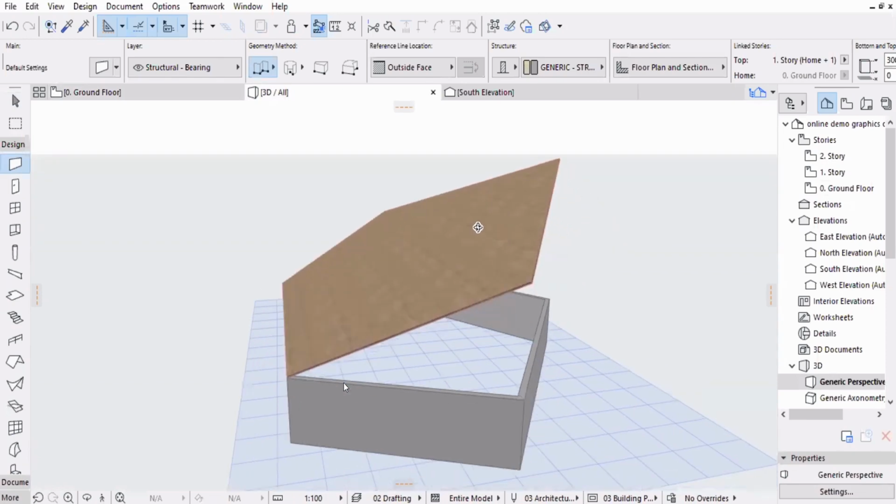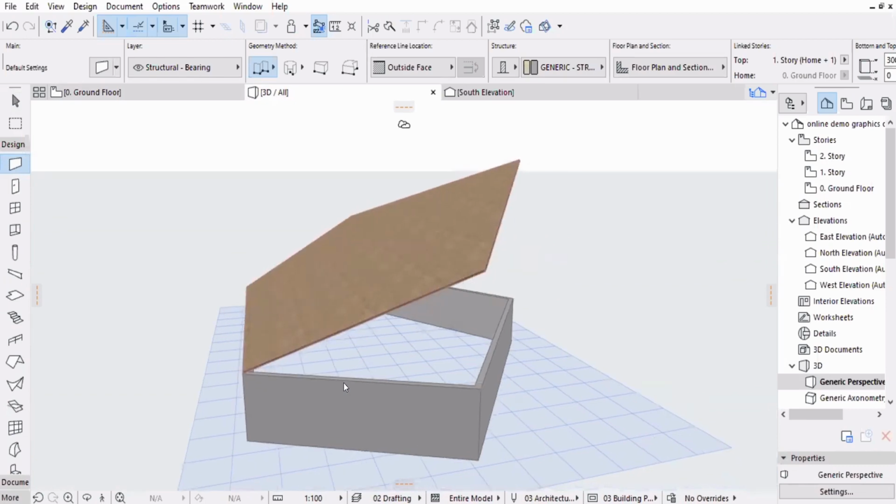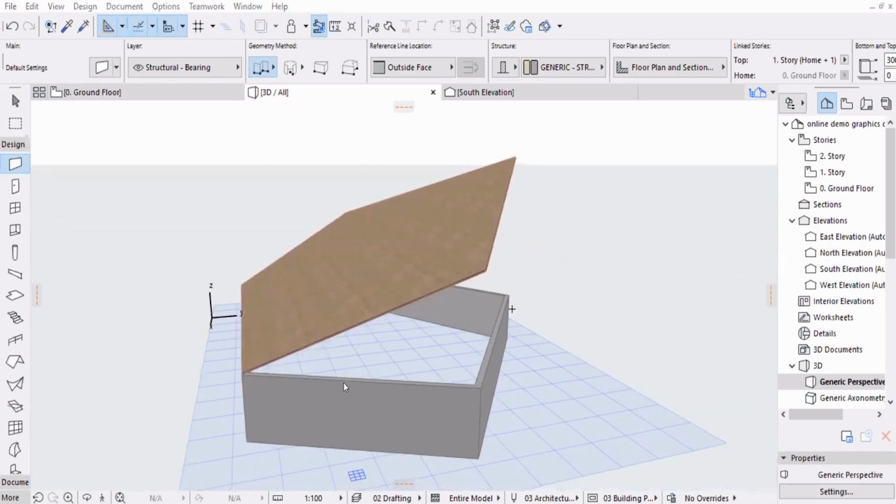So let's do that. For that, what is also very important is, if you need to cut, you're going to use the plane as a trimming object for the walls that are extended beyond the roofs. So for that to happen, you need to make sure the roof edge is not just in line with the wall. It is projected a little more.